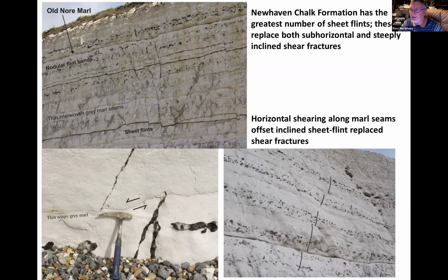So when I'm asking the loggers and the SI contractors to pick up all the Marl seams, I'm not asking them to do it just for fun. These little thin seams actually have a huge impact on the mechanical properties of the rock mass.